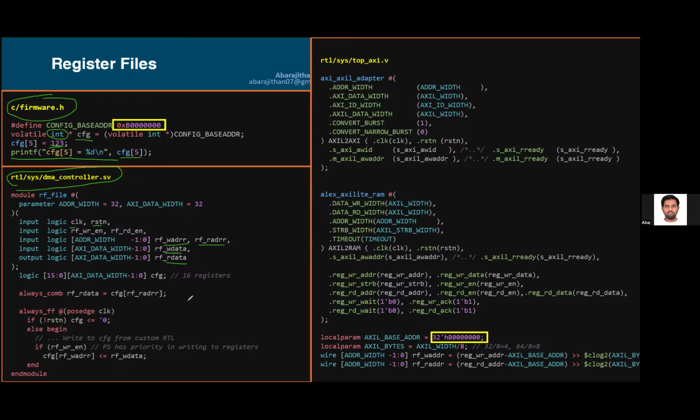Okay, right. So now the actual register is defined like this. It is logic. You have 16 registers here, and each of them is XC data width wide. What is XC data width? It is 32, and we are using 32, that is the size of an int. So you have int size registers, and you have 16 such registers in total. Your actual data is going to live inside this variable, the configuration registers, in Verilog.